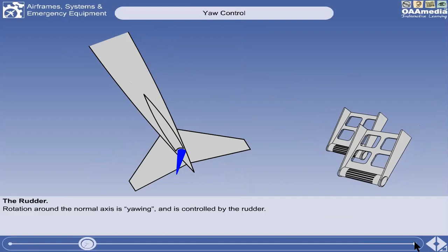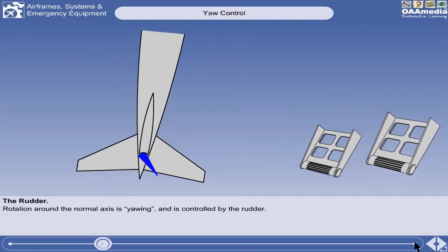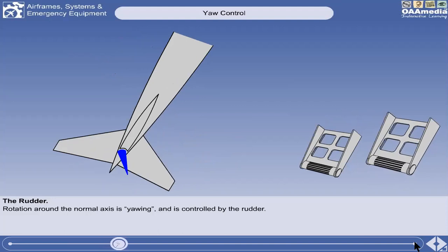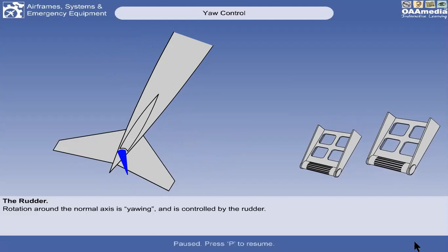The rudder is required to maintain directional control with asymmetric power, to correct for crosswinds on takeoff and landing, to correct for adverse yaw, to recover from a spin, and, on a single-engine aircraft, to correct for changes in propeller torque. Okay, one method of correcting, for example, for a single-engine aircraft, your engine is in the nose portion, it creates a torque. Okay? Meaning the torque has an effect on our aeroplane.